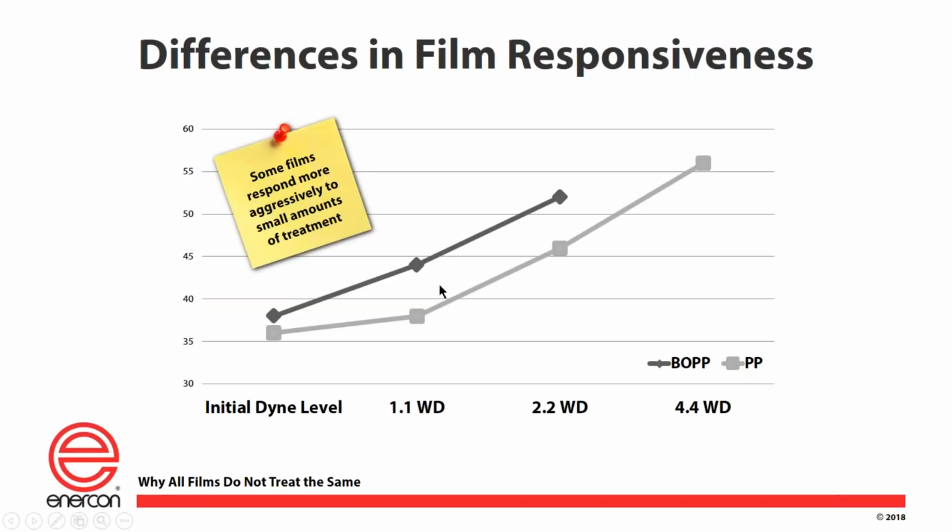Are we referring to the film being treated as a cast polypropylene, which might have one characteristic, or are we dealing with an oriented polypropylene, both biaxially or just a standard oriented polypropylene, single orientation, that might exhibit a totally different characteristic? And so in this slide, you can see what happens. And of course, if you look at the slide, you can see where the confusion comes in and why things don't appear as simple as sometimes people assume they are.